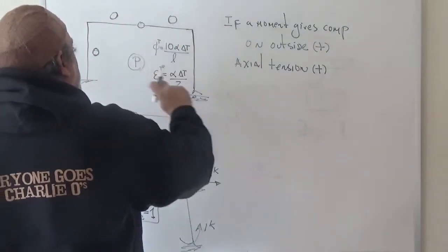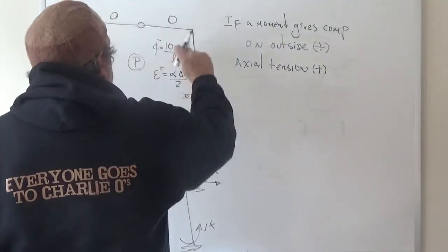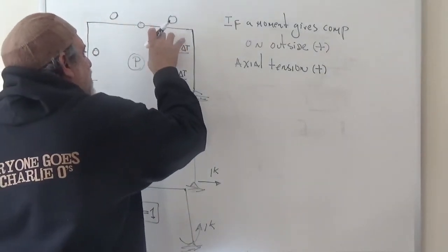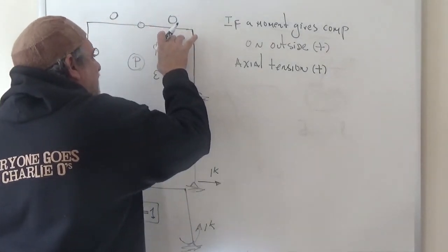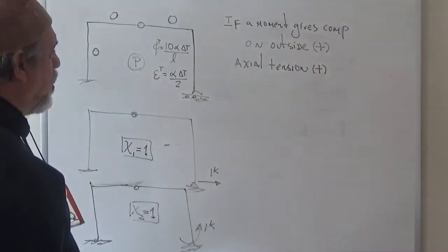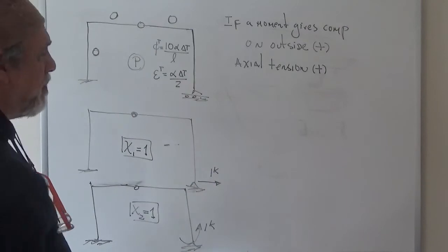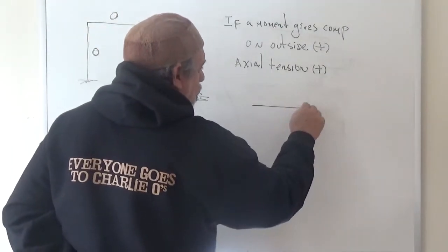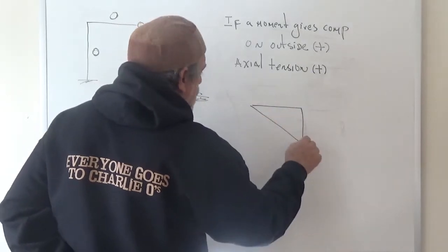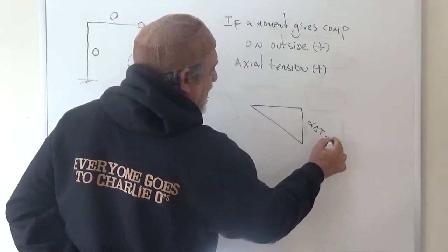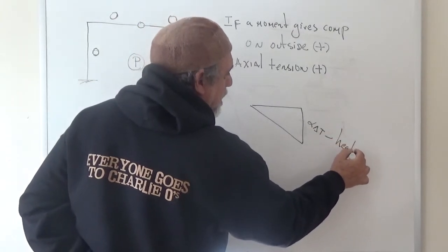have already the effect due to, if you had moment, it would give curvature. We have to decide what is the sign that we should give to that curvature and what is the sign that we should give to that axial temperature induced strain, given this convention. So again, remember that the temperature distribution over the column was like this, with alpha delta T, and this being a heating, right?